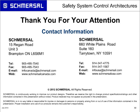Can you achieve a Category 4 with a variable frequency drive instead of a mechanical motor starters? Instead of two mechanical motor starters? I hate to do this, but I'm going to defer this answer to the variable frequency drive manufacturer that you would be using. I can only tell you what I typically have seen. What I've seen is they achieve up to a control category 3, performance level D in their ratings, but I'm not going to say that there aren't drives out there that can achieve a control category 4.